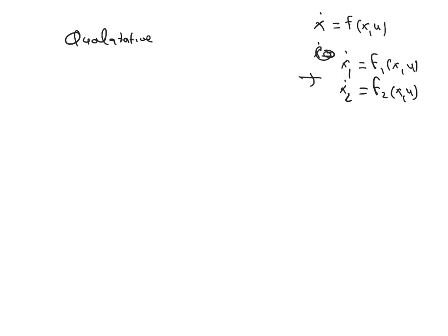Even solving this, I remember when you were doing time varying systems and you had to find that state transition matrix, it was a pain in the butt, right? And that was a linear system, even if it was time varying. Now you're solving for nonlinear systems, even if they are second order. Getting an exact solution is not possible. That's why you need the phase plot, approximate plots that can help you visualize how the system is converging or behaving, right? So qualitative behavior.